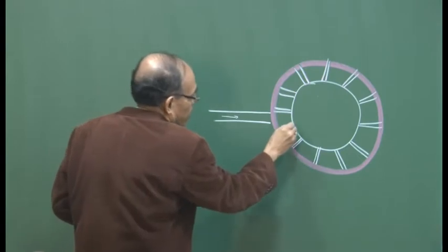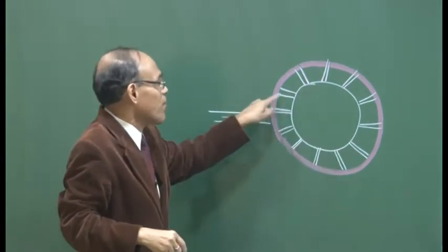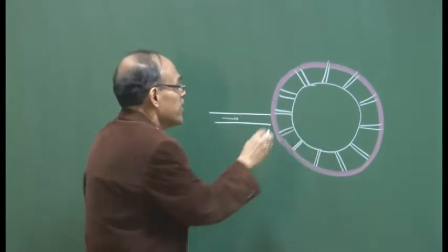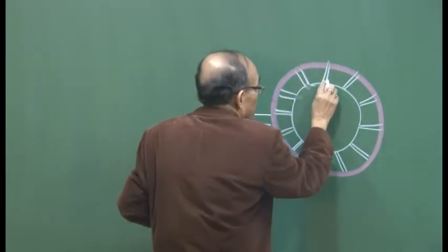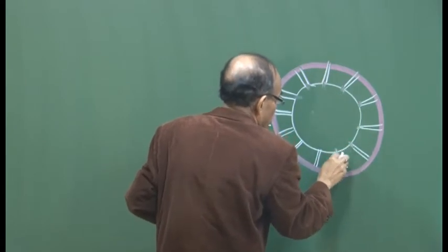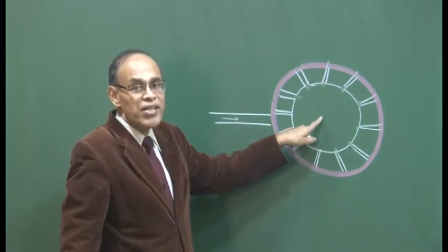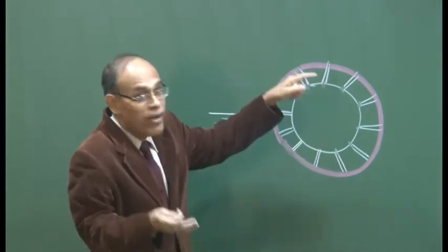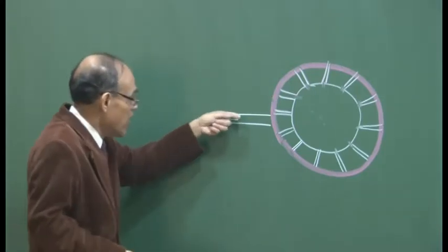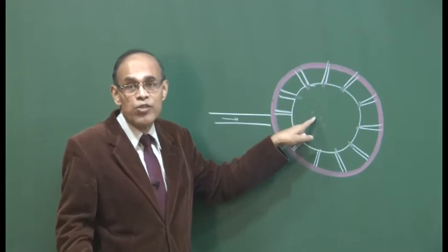This is the way it is. So, there are several such tuyeres connecting the bustle pipe and delivering the air inside the blast furnace. Okay? And you can imagine that the blast will never be able to penetrate to this diameter, if this is 30 meters, and you have such a huge resistance in the path of the gas. You can imagine what should be the force of the compressor in order to drive the air right up to the center core.